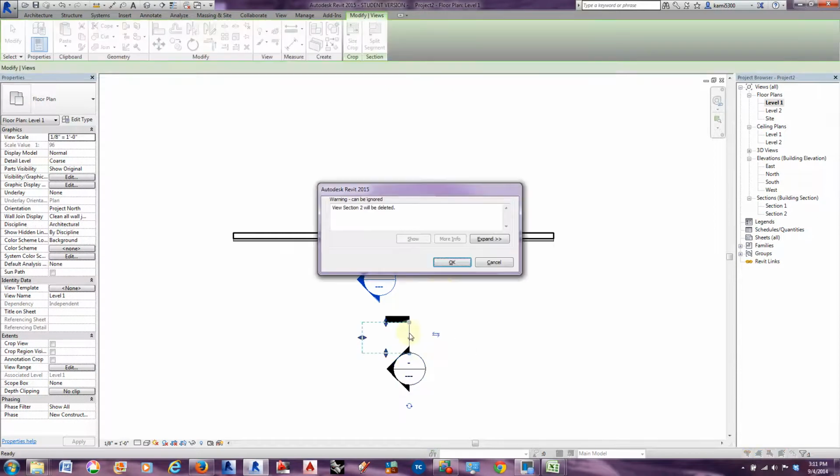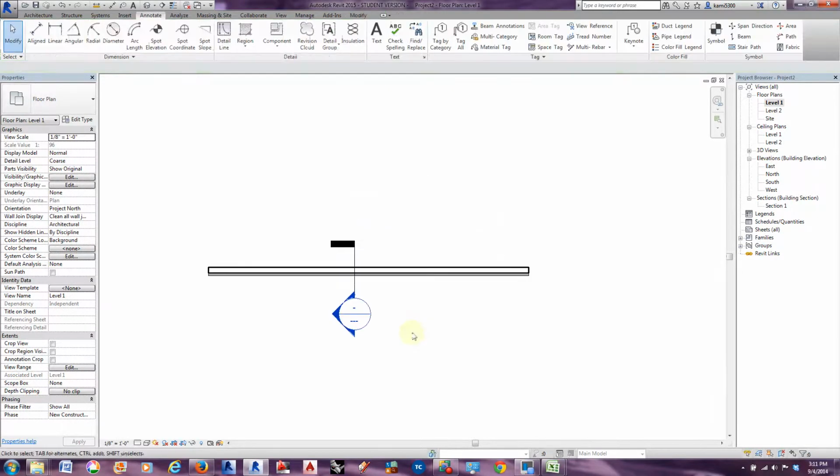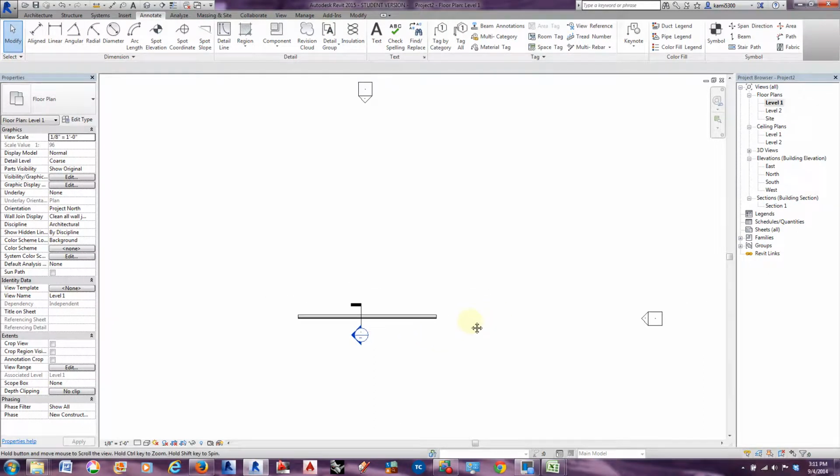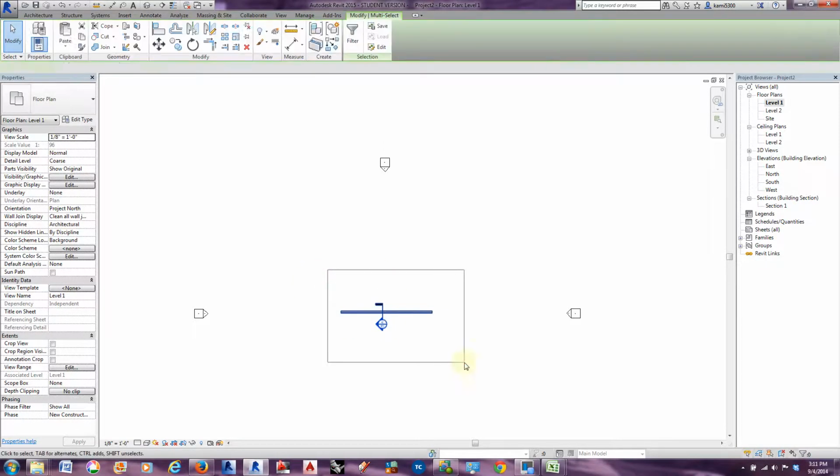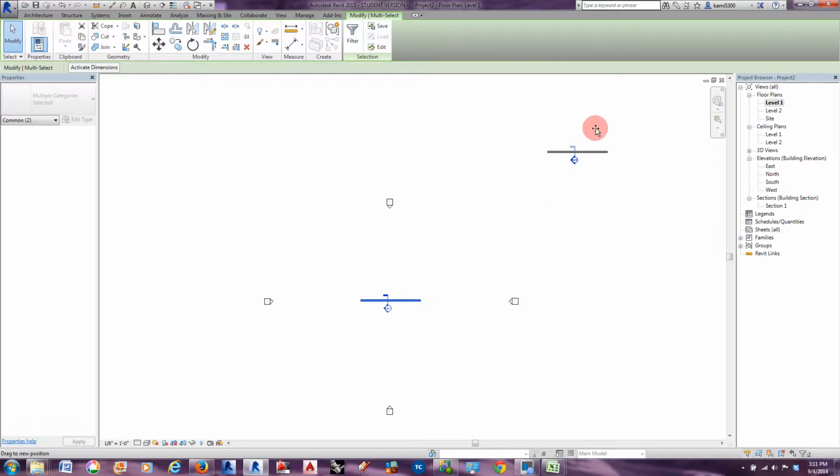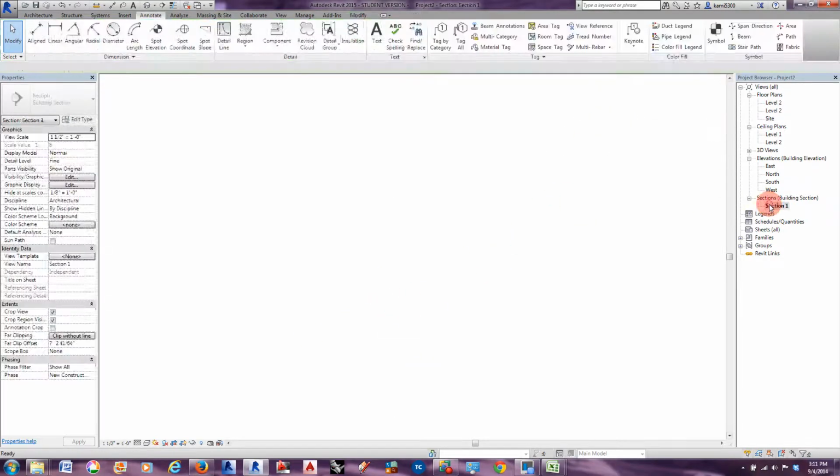And so go ahead and create all the different types of roofs that come up in the video, and use this stacked wall as your 4 walls for all the particular roofs. And keep this section somewhere off to the right or whatever. You can just right click it or left click it, drag, and move it off to the side so that it still exists and you don't lose that guy.